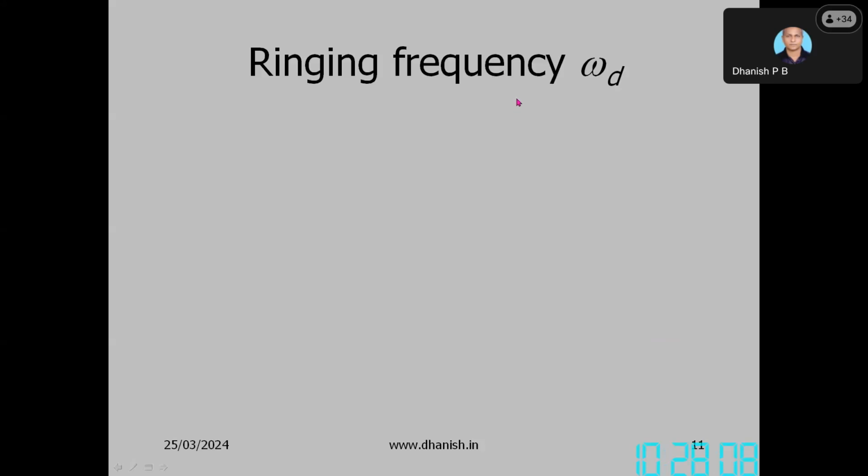Next we come to ringing frequency, omega d. So what is ringing? We are giving a sudden step change to the instrument. Like a bell, you are giving a hit to the bell. So what will happen? The bell will ring. With what frequency? That is your ringing frequency, omega d.